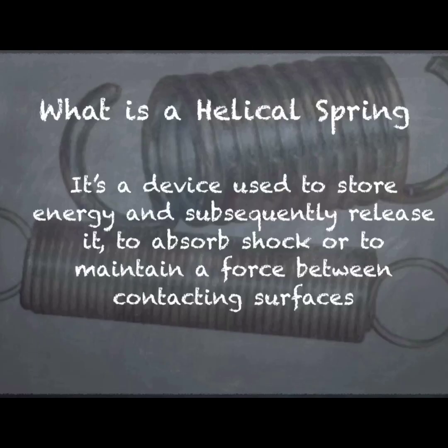A helical spring is a mechanical device which is used to store energy and subsequently release it to absorb shock or to maintain a force between contacting surfaces. Here, the energy stored and released by the spring is understood by the application of Hooke's law.